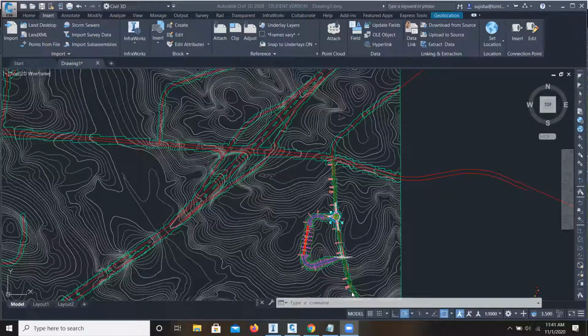Okay. And we can also export to BIM software, right? Yeah, you can export to Revit software and all. You can directly export everything to the Revit software. If you have any model in the Revit software, you can bring that model into InfraWorks and place it. If you are working on urban planning, you can create your models in Revit, bring them to InfraWorks, place them, and develop or prepare that area with all the buildings, roads, and bridges. If you want any culverts, drainages, everything can be done, and you can create the presentation and everything. Okay, madam.